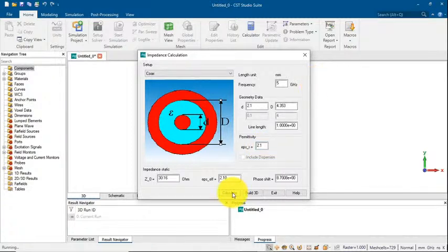You see, you calculate the impedance. Maybe you want to change this to get an impedance. Okay, change the impedance. You want 50 ohm, you will play with this 1.7, for example, to get impedance close to 50. Okay, we want 50, so we can choose everything we want. Okay, anyway, this is a type of impedance calculation. Let me press X or exit.